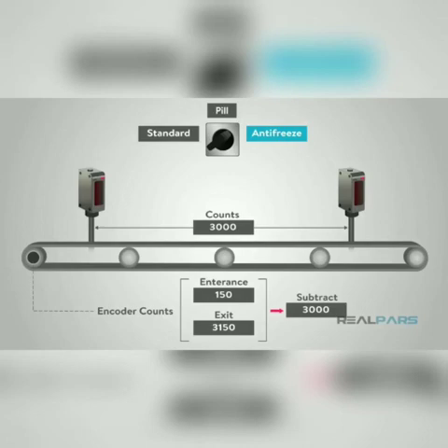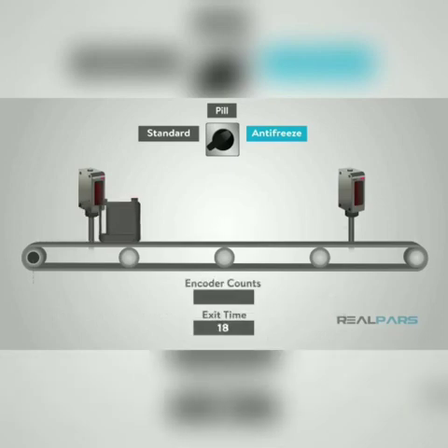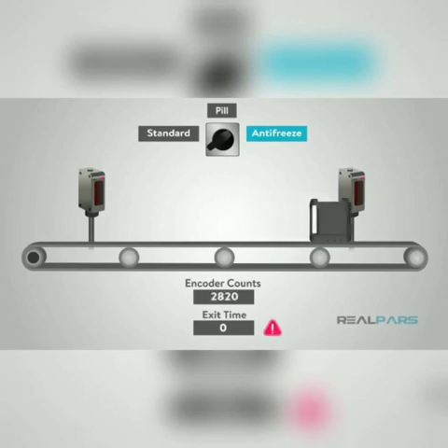When back in run mode, the code knows that there's a handle to ignore when it comes into the process, and doesn't fault the machine. You register the encoder at each bottle entrance and predetermine when the bottle must exit. If the bottle doesn't exit the machine in a timely manner, which is based on your projection and the current encoder count, the machine faults. This is a great use of an encoder that is fully configurable. Count in, count out, subtract, done.